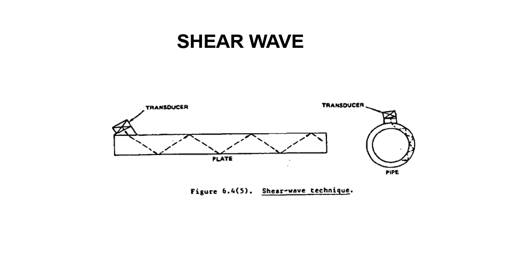Angle beam techniques are used for testing welds, pipe or tubing, sheet and plate material, and for specimens of irregular shape where straight beam units are unable to contact all of the surface. Angle beam transducers are identified by case markings that show the beam direction by an arrow, and that indicate the angle of reflection in steel for shear waves.